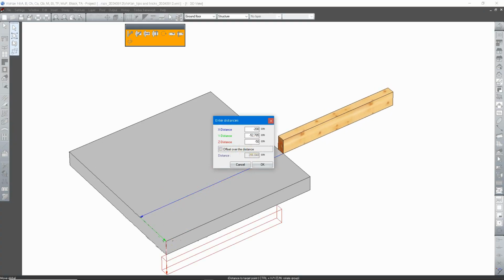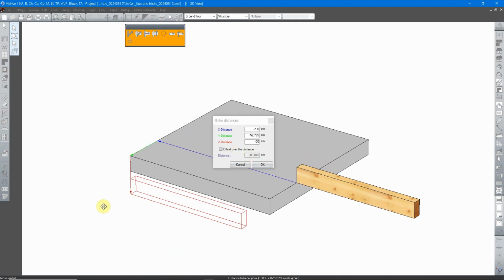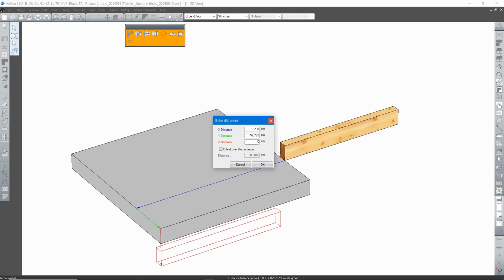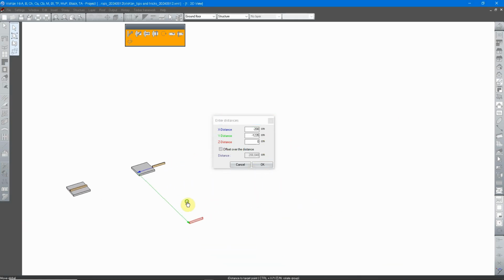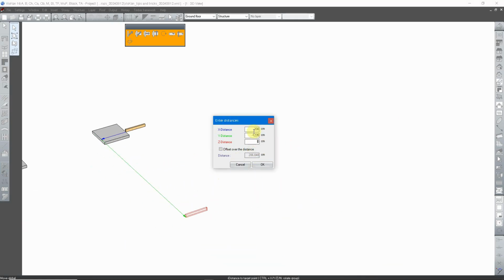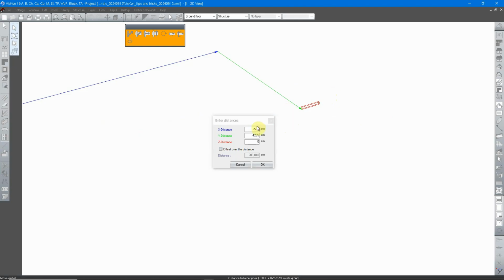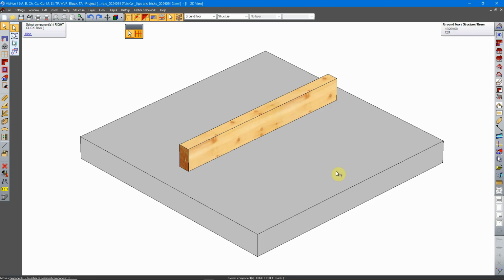Or with a negative parameter, it goes down below. Obviously, I can type any number if I want to, and I will immediately see the preview of where my element goes if I press the tab button. This is the move action.